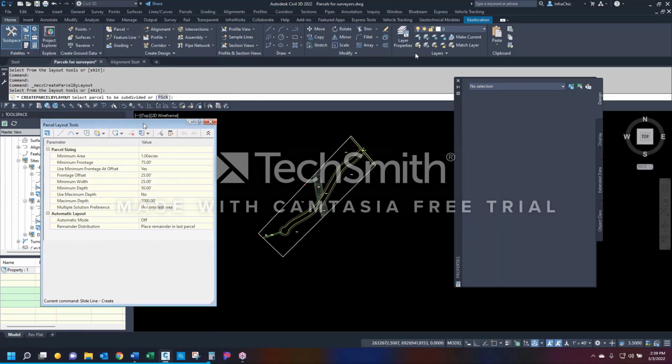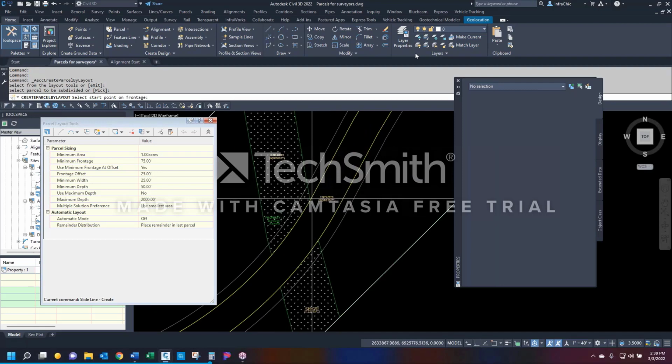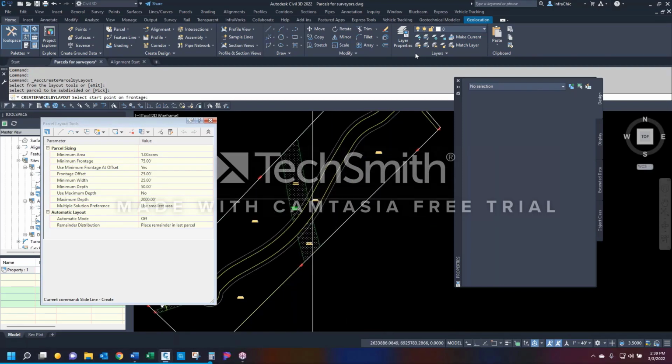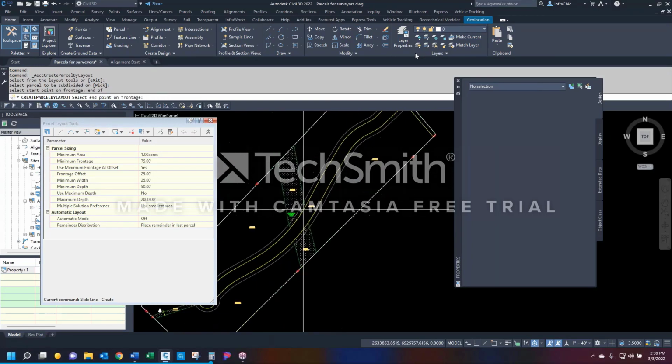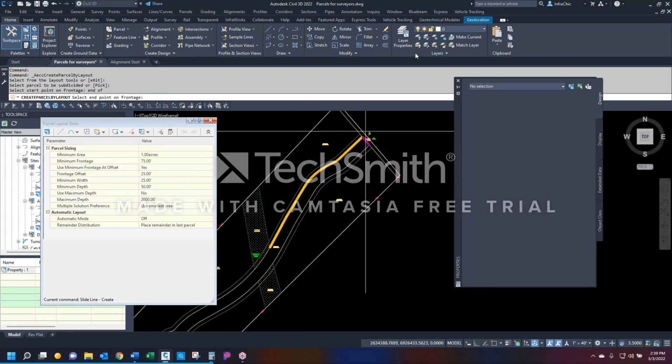Now, I'm going to move this out of the way. Select the parcel to be subdivided or pick. So it means select the parcel area label, not the line work, the label. We'll start at the front. Okay, it said it found it. Now, select a starting point on the frontage. The frontage is this line, the yellow roadway boundary line. I'm going to choose end, typing in end, enter, grabbing a point. This is my jig line, and I will follow it to the other end.